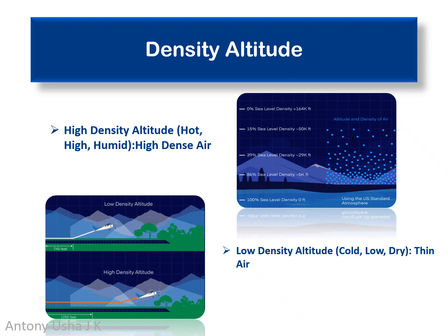Density altitude is not a physical height, but rather a performance altitude. It's defined as the pressure altitude corrected for non-standard temperature. Essentially, it's the altitude at which the aircraft feels like it's performing.